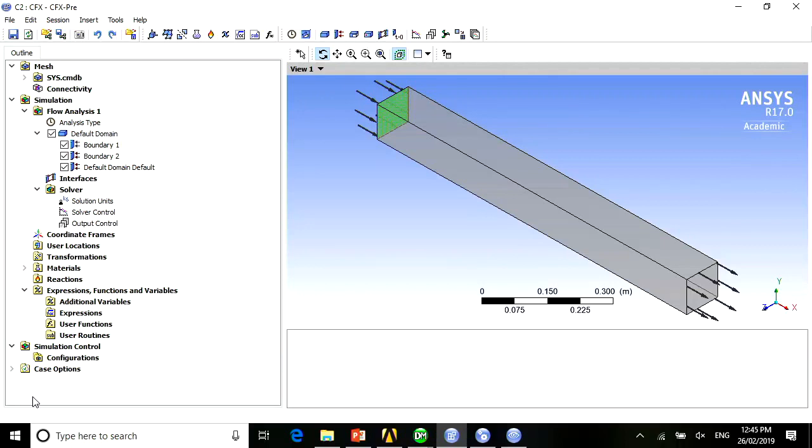By definition, those people who know fluid dynamics know that the Reynolds number is the density times the reference velocity times the reference length, divided by the dynamic viscosity. If it's anything less than 2,000, it's going to be laminar for this type of geometry, more of a conduit.